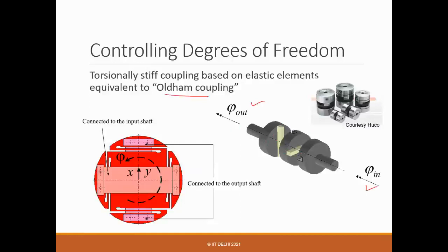But of course, they are all moving members, and they have physical contact and a lot of friction involved. So for a heavy application, for not so precise application, use it, but immediately you can convert it, because in principle all couplings are designed based on kinematic constraint requirements, and you just have one constraint, the rotational constraint. So if you want to convert, you can convert using flexures.